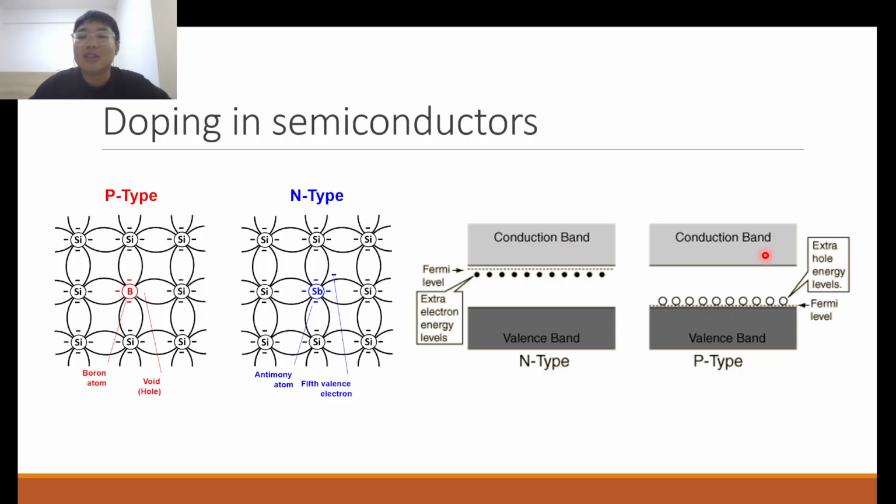Okay, and just one point to note, the y-axis, the vertical axis of a band diagram, is always electron energy level. So electron moving up takes energy, but remember hole has the opposite charge of electrons. So hole moving down in the electron energy level represents an increase in hole energy. Okay, so moving electrons up takes energy, moving holes down takes energy in the band diagram.